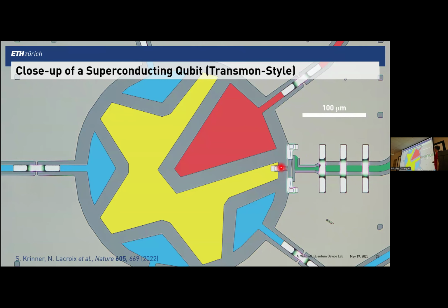And I think the important point is that when the qubit changes states, you have a displacement current, and the displacement current needs to be able to flow around your qubit, so you need to make sure that it's connected all the way around. In some of our designs, we decided to have this connection in the base layer metallization, and maybe this was driven a little bit by our initial belief in the reliability of this air bridge process. And we have the reverse, and if your air bridge process works well, I think this should not make a difference.